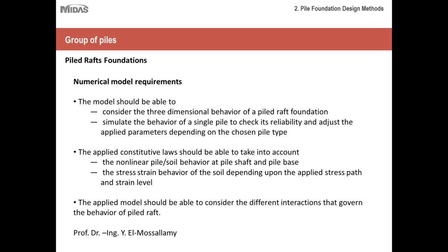Then the second most important requirement is that the applied constitutive laws should be taken into account, and those laws should consider the nonlinear pile-soil behavior at the pile shaft and pile base. The stress-strain behavior of the soil depending upon the applied stress path and strain levels should also be considered.